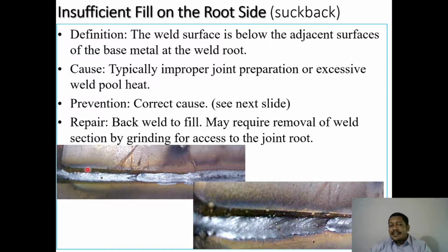Instead, it will get melted and vaporized off. Due to the excessive heat, the material on these edges or sides may get melted and vaporized off, so the joining is not taking place. Either the gap is high, or the excess heat causes these kinds of defects in welding.